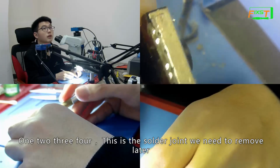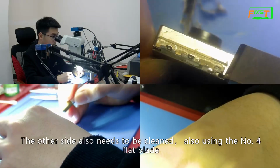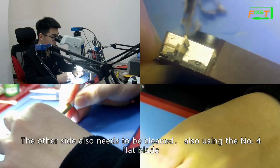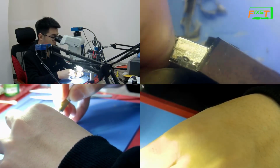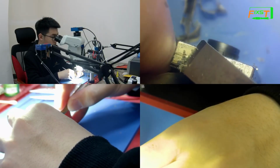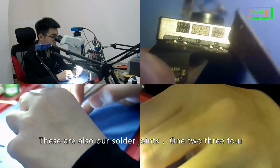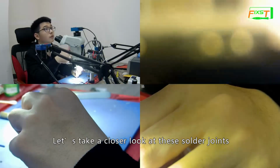This is the soldering joint we need to remove later. The other sides also need to be cleaned, also using the number 4 flat blade. Okay, there is no glue on this side, no need to clean up. These are also our soldering joints. 1, 2, 3, 4.